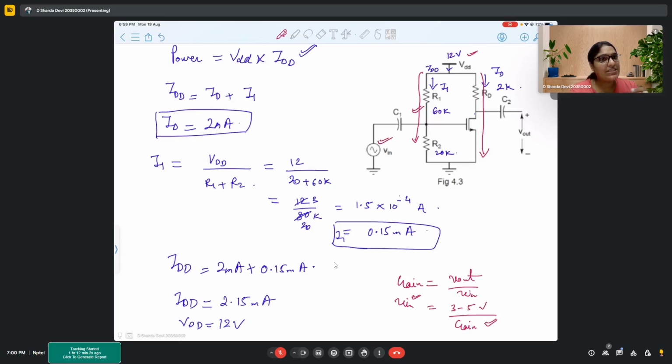So there might be a few sensors which are very sensitive, right? And those sensors will have very small peaks, and those peaks need to be amplified. So those can be picked up by these large gain amplifiers. So the idea is that it basically increases your input signal range, if you can understand that.